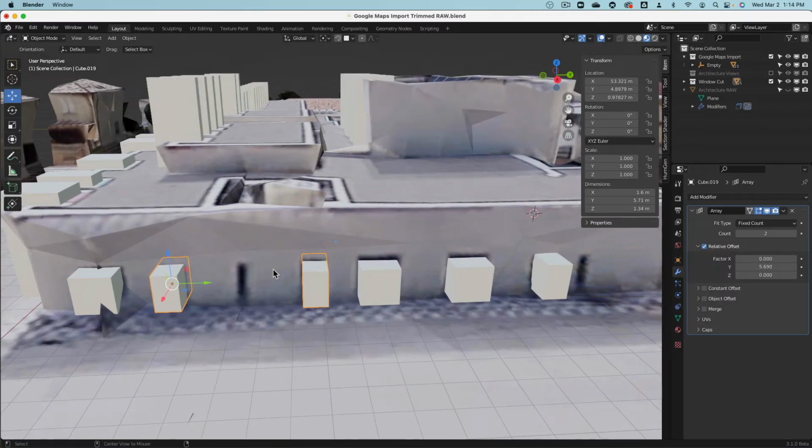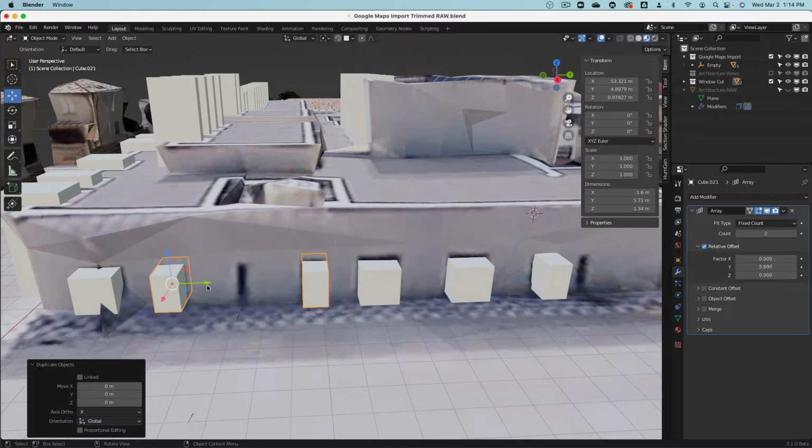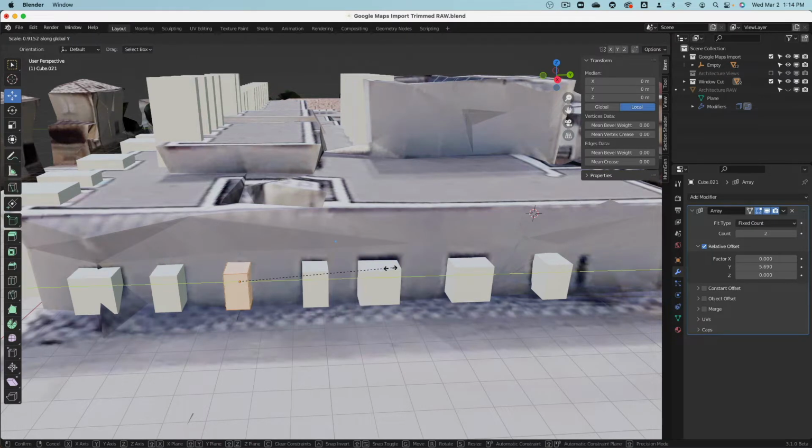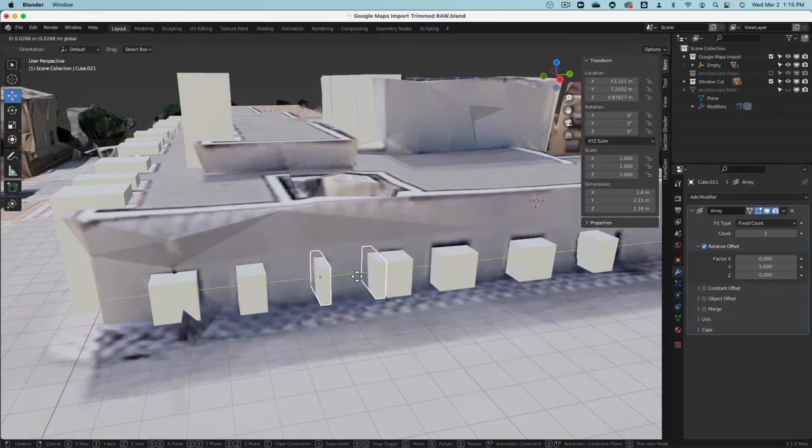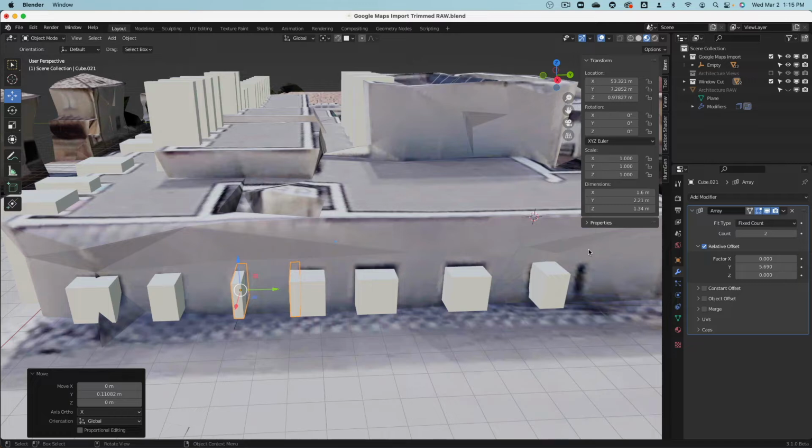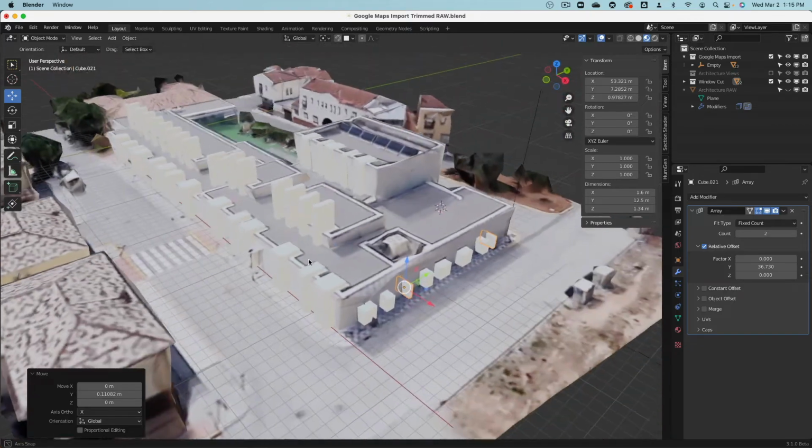Last one, Shift D, escape, bring this over to there, edit mode, S and Y. You notice how it's kind of like mass production. Some commands to know, learn at the beginning, and then once you know how they work, what they are, it is really working it off.